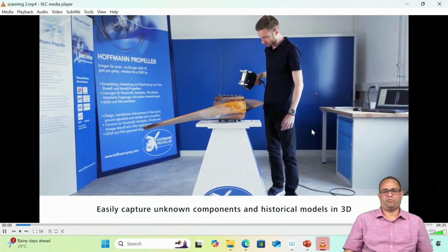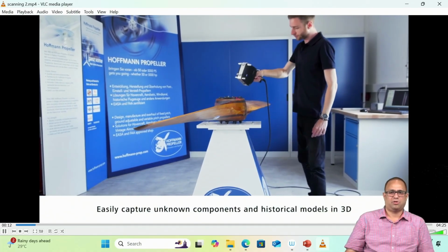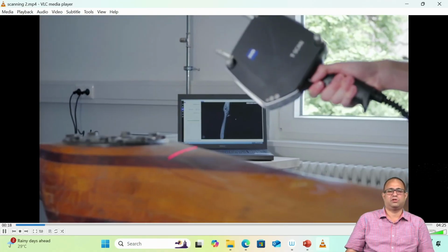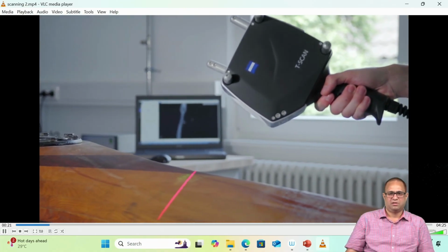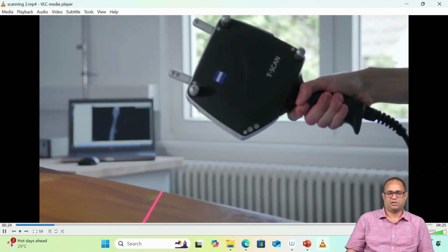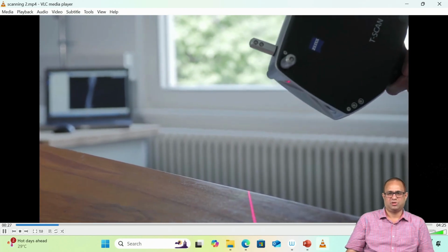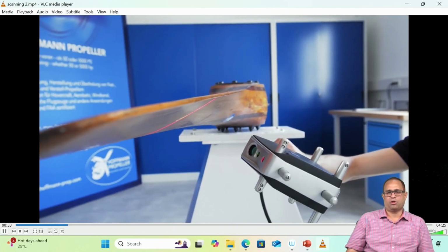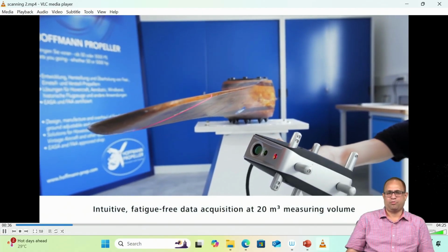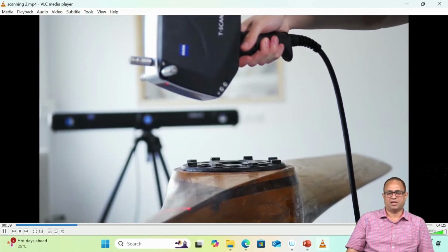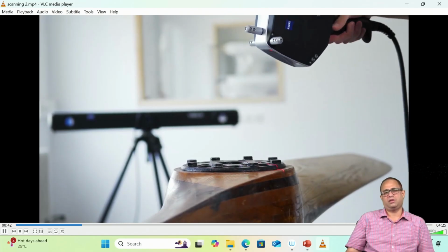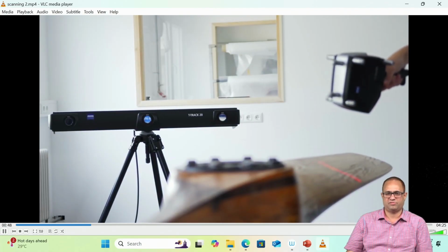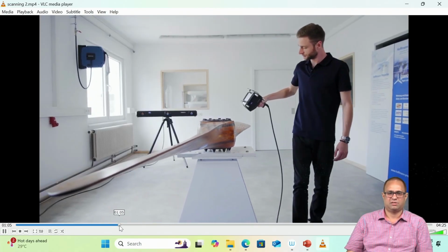And this video is also one more non-contact scanner. Here, how big parts are captured with the help of a laser light focused on the surface of the physical model, as you can see here. You can see the capturing being done in the system also. This scanning technique needs a lot of technical experience: how we are going to scan, in what pattern the scan has to be done, etc. Later, there is the processing of the noise factors, etc.